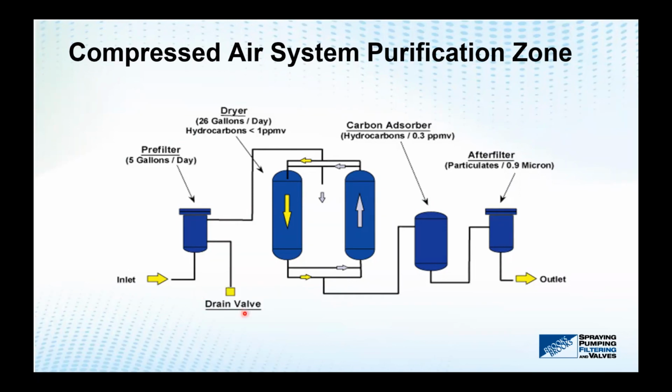Also, with new technology today, and we'll elaborate a bit more on that on the next seminar, in the past they were always timer-based drains. So, with seasonal changes, the amount of liquid coming out of the drain valve varies between summer and winter time. In the winter time, the air at the inlet to the compressor is relatively dry.